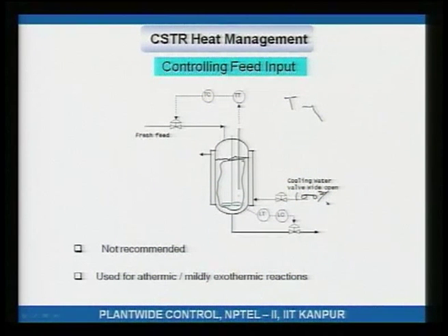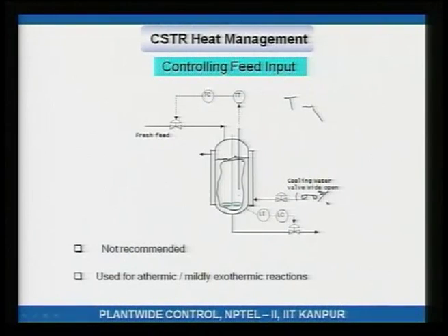Of course, because of the large mass stored in the CSTR, this increase in concentration will happen slowly, it will not happen immediately. Then, because a sufficient amount of material has accumulated, or the concentration has gone up sufficiently, the amount of heat released will start to increase because the reaction rate is increasing. Now, because heat released increases, temperature starts to go back up.